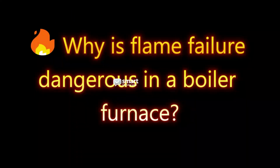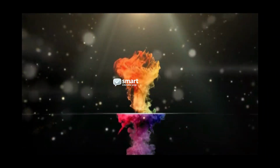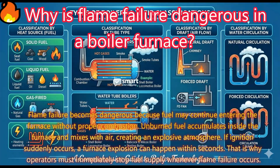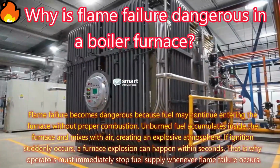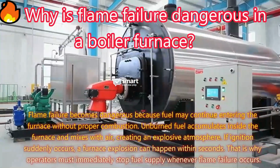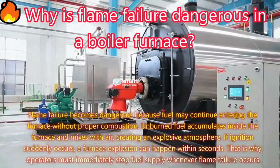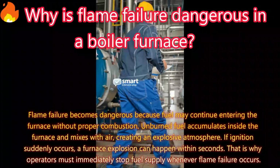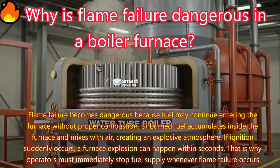Why is flame failure dangerous in a boiler furnace? Answer: flame failure becomes dangerous because fuel may continue entering the furnace without proper combustion. Unburned fuel accumulates inside the furnace and mixes with air, creating an explosive atmosphere. If ignition suddenly occurs, a furnace explosion can happen within seconds. That is why operators must immediately stop fuel supply whenever flame failure occurs.